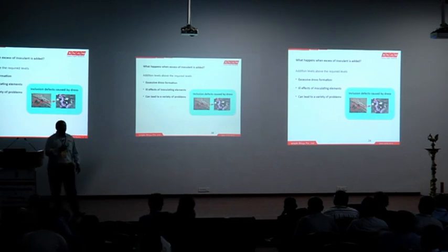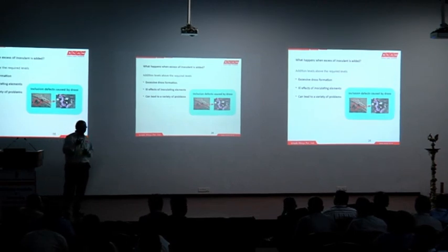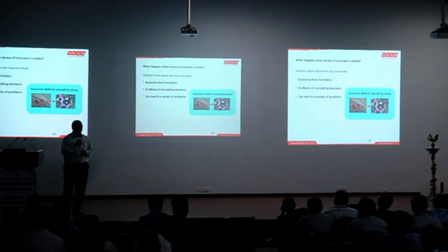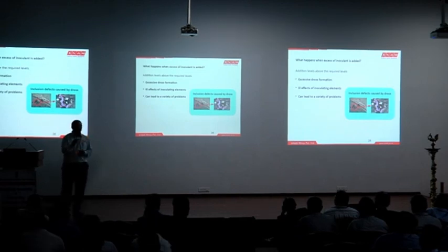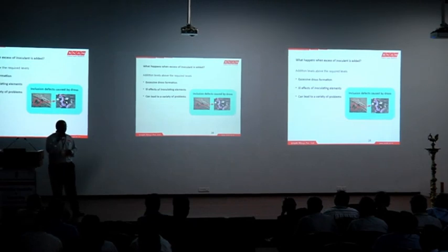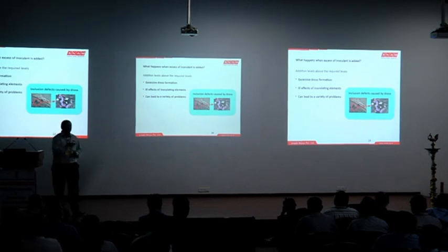The list of elements I had shown previously are strong oxidizing elements. So by default, when you take liquid metal to a temperature close to 1600, oxygen influx happens and you start getting oxides in your liquid metal, nascent oxygen. When the temperature comes down, oxygen cannot stay, it starts reacting with elements present in the liquid metal and forms compounds. So we can call it oxides, you can call it slag, or slag is made of silicates. Silicate is again an oxidized form of silicon. So ultimately it revolves around oxygen.